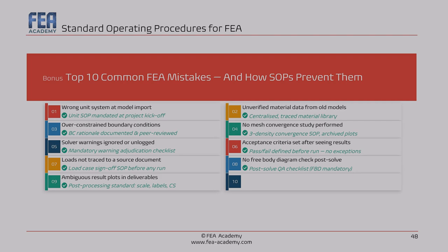And this is valid for all the extractions, the stress extraction, the strain extraction. You document whether the stress is an average stress, von Mises, principal. Be explicit, okay?